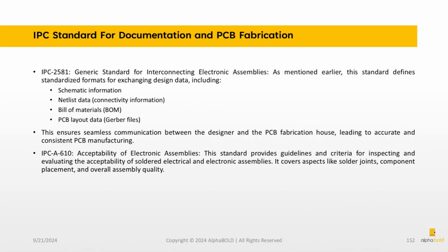IPC 2581, Generic Standard for Interconnecting Electronic Assemblies. As mentioned earlier, this standard defines standardized formats for exchanging design data, including schematic information, netlist data, connectivity information, bill of materials (BOM), PCB layout data, Gerber files. This ensures seamless communication between the designer and the PCB fabrication house, leading to accurate and consistent PCB manufacturing.